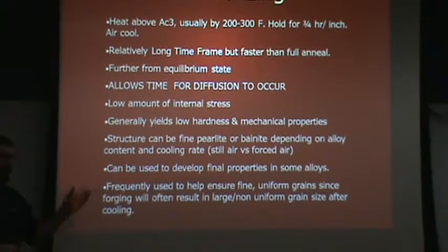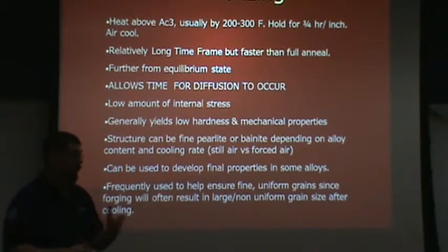Not with necessarily these alloys, with other stuff. I mean, if you're talking about turbine blades, they actually want a single crystal, that's just because you don't want creep to occur with the high temperature, high stress that the parts are undergoing. Right. So a single crystal is the best example. That's the biggest.